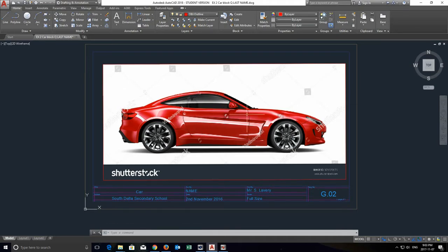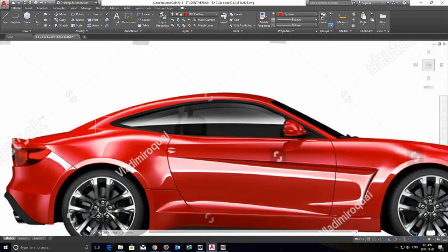Now, how are we going to draw this? Well, remember we had lines and polylines and circles. Well, that sure is not a polyline. That is not a line. That's a nice curve. Now, how we can actually draw those curves is a really neat little technique. What we're going to do is go up here and click on the Draw menu. I'm going to pull that down. So here's some more drawing options. This is the one I want in particular. This is called a spline fit. And it's easier to show you what a spline fit does. So I'm going to click on that.